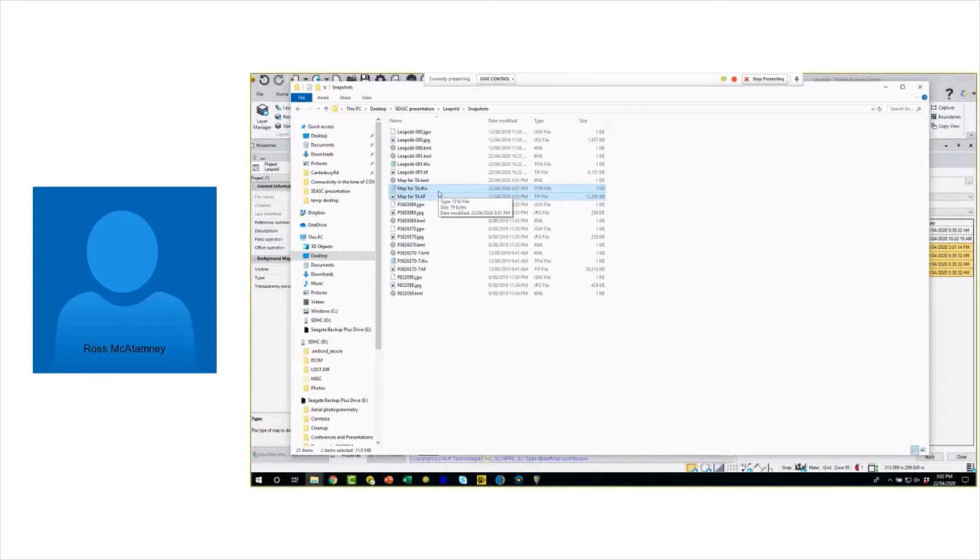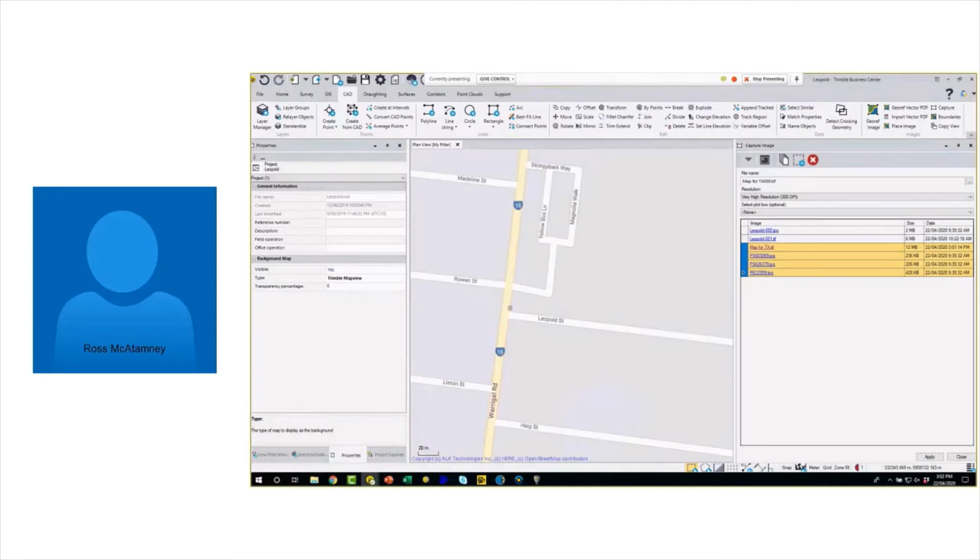You can get these from different government agencies; sometimes they provide an aerial image or a background image as a TIFF file containing a TIFF world file as well. But if you don't have that through your government agency, then a simple version is using the Trimble Business Center embedded background maps, just doing a capture and then utilizing that to take through to the field.